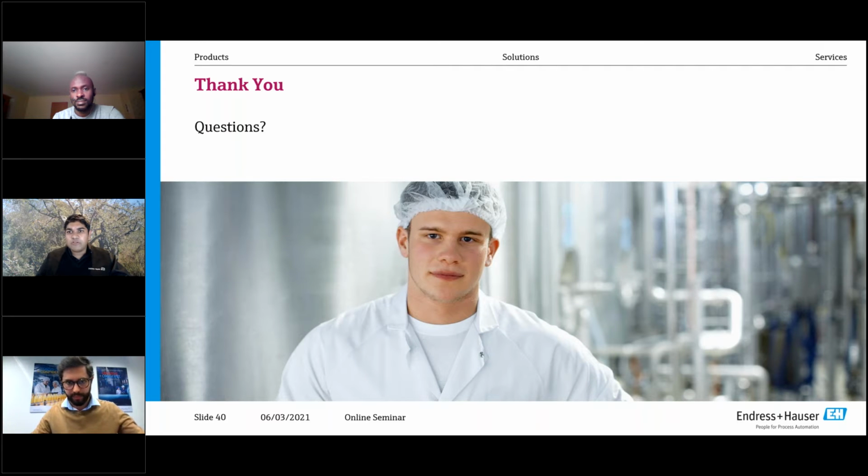Samson, I see you ask, how often do these sensors get calibrated? I'm not sure which sensors you're referring to, but calibration intervals depend on the process running in the plant. As an example, for temperature, the rule of thumb is once a year. pH, on the other hand, I've seen calibrated sometimes once a week, sometimes every month. So if you want, you can get in touch with me and we can chat about how often a calibration should occur.